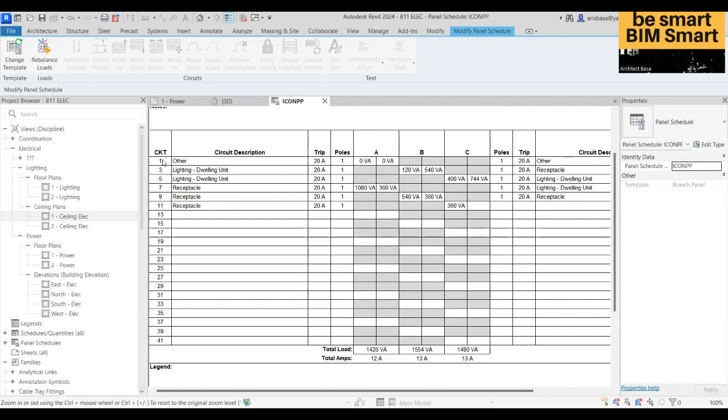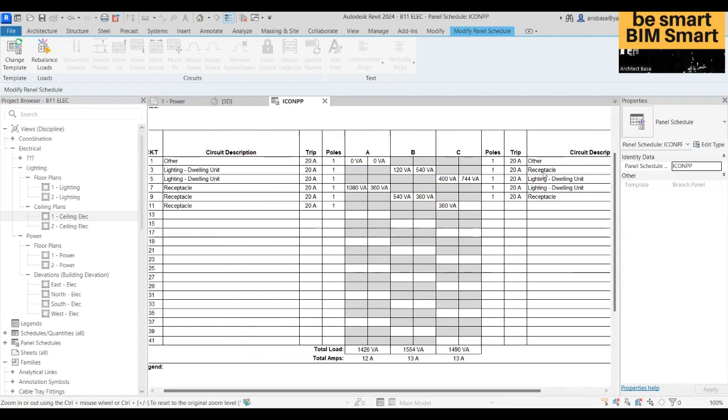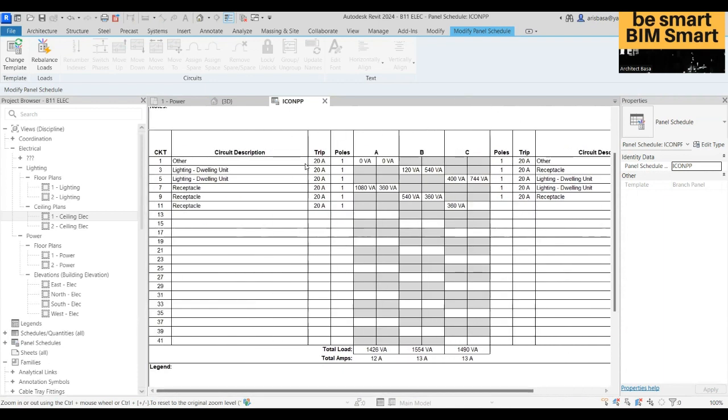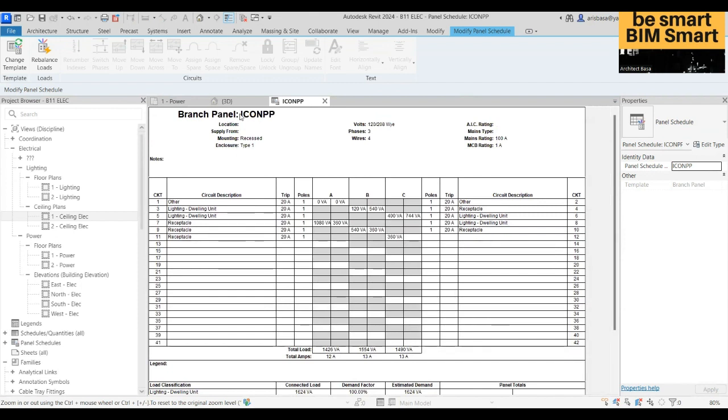Now, the breaker here is here. Each circuit will have a breaker, right? So this is the panel schedule. You have the circuit here and another line right there. This is a ready-made template. It is telling you this is the panel like that. If you see it in buildings, in hotels, each of those panel boards will show like this. Which one is that? What number? So that if something trips, you know which one to replace or repair, right?